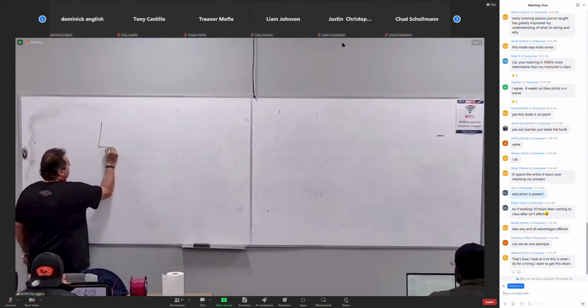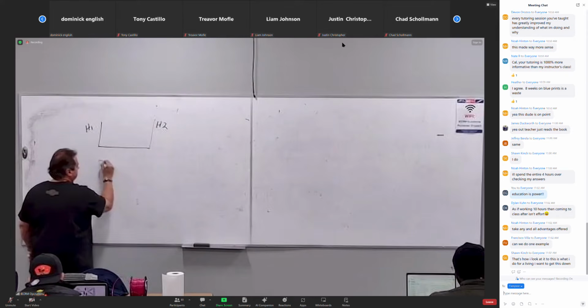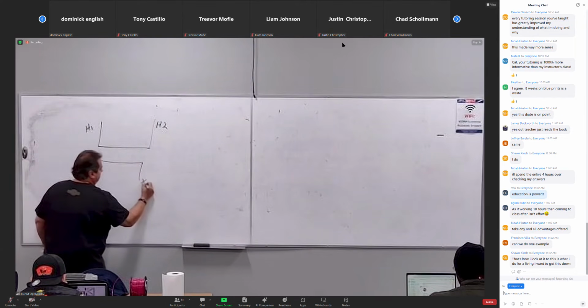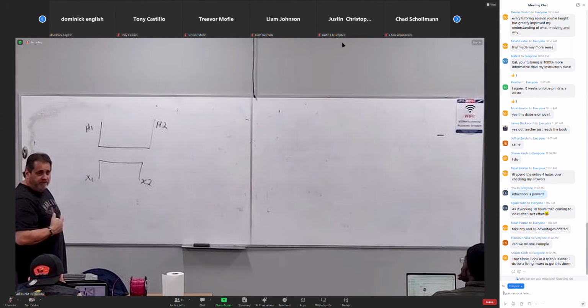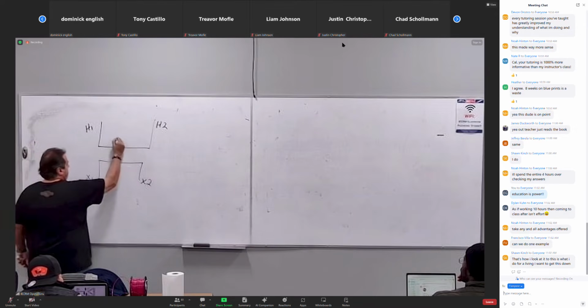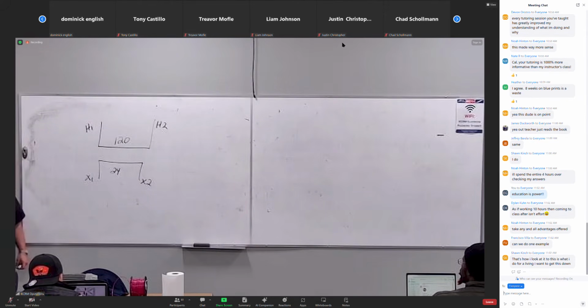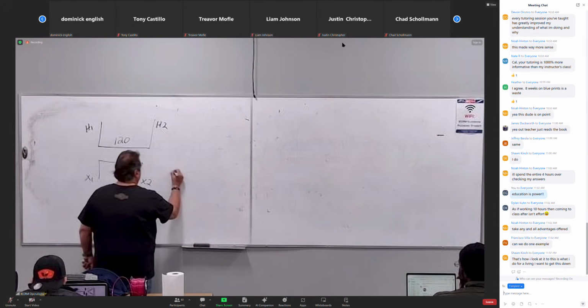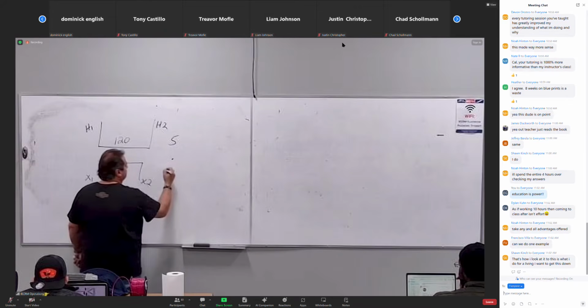On a single phase transformer, I'm gonna draw them pretty basic. I draw them like this, H1, H2. Even though the book does it backwards, it's okay. And once again, everything starts in the transformer with turns ratio. 120, 24 volt. How do you solve for turns ratio? The way you solve for turns ratio is take the smallest number and divide it into both. Yep. Best way to do it. 24 into 24 is what? 1. 24 into 120? 5. It's a 5-to-1 voltage ratio.